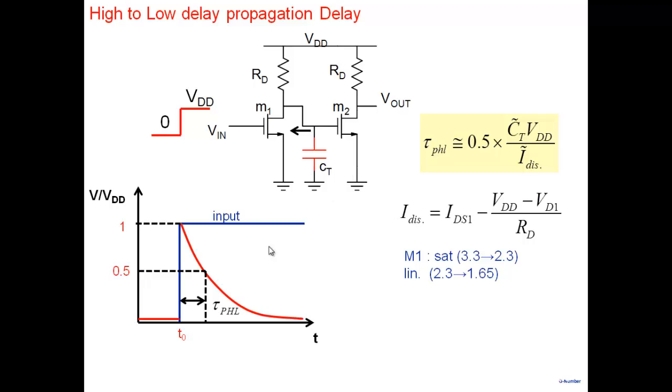What I'm interested in is calculating the discharge current at these two points and taking an average, to do a very quick calculation. The discharge current in the beginning, the transistor is in saturation region, so it's Kpn W by L times (VDD minus VTHN) square by 2. It's straightforward, I can very quickly calculate once I have the size of the transistor. VDD is known, VTH is 1 volt. I can calculate this current. What is the discharge current at this particular point here?